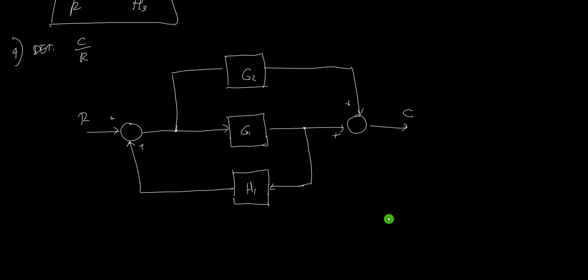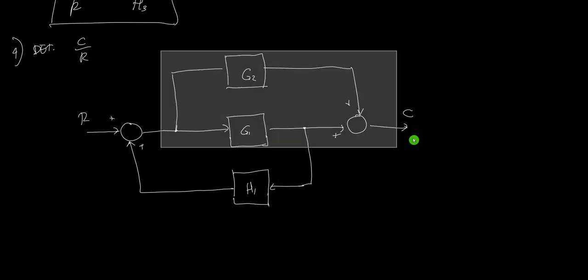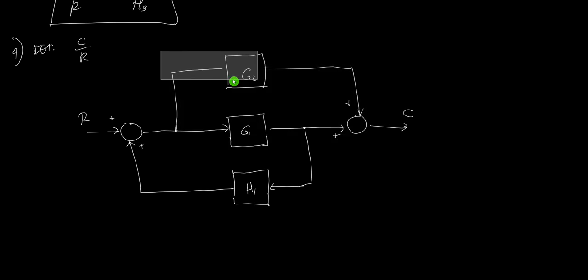This one looks like a simpler example compared to the previous examples, but it is harder to simplify. Why? Because there's an overlapping between these two canonical forms. So we cannot just say that this part here is in canonical form, because we have a take-off point somewhere here. Also this one. So the solution is to apply our rules.